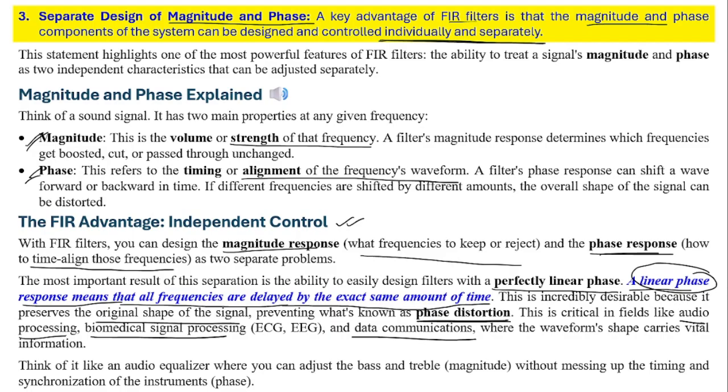So there are several sinusoidal signals. One signal is delayed, another is not delayed. So at a particular point, you will have different frequency components all together, and they can add up. Due to that, you will have a distortion of the signal, and that is called phase distortion.